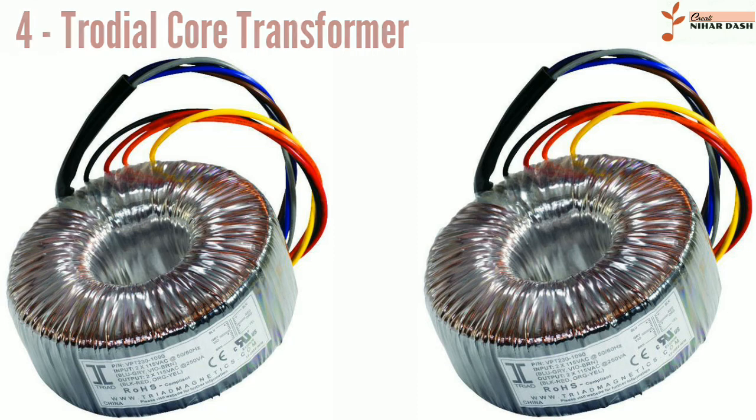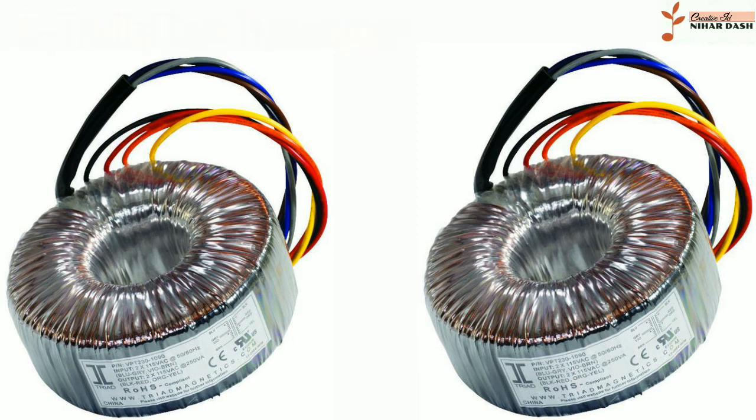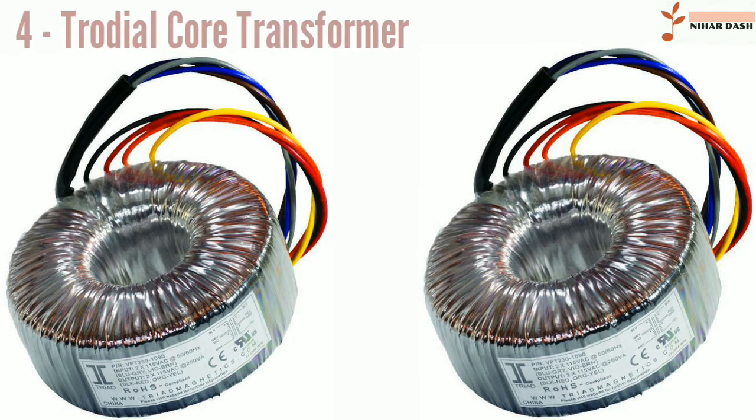Small distribution transformers may achieve some of the benefits of a toroidal core by splitting it and forcing it open, then inserting a bobbin containing primary and secondary windings.